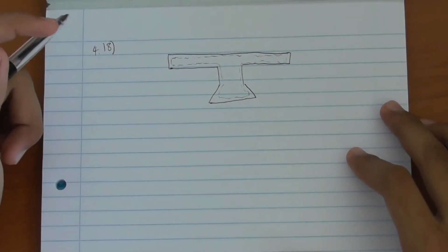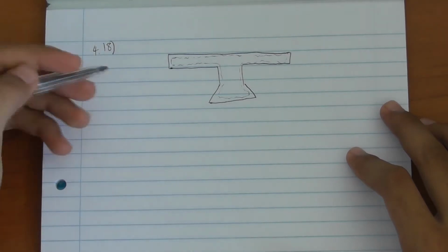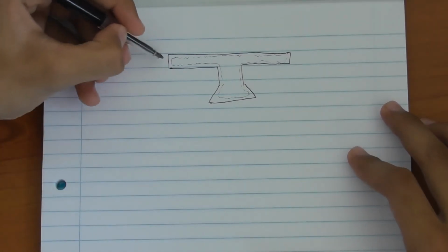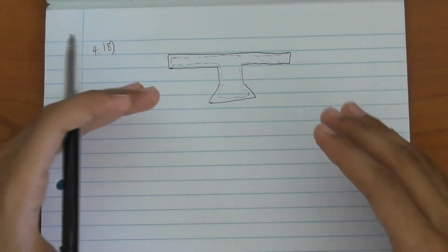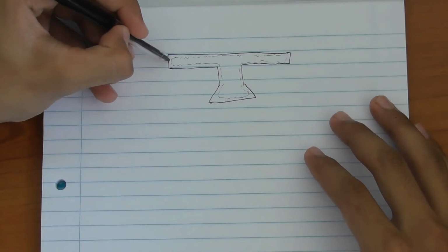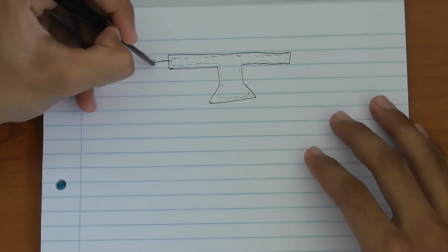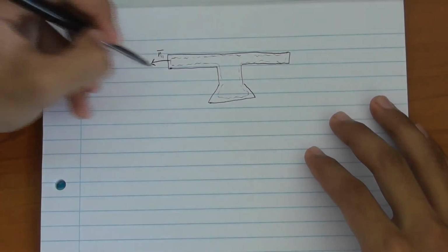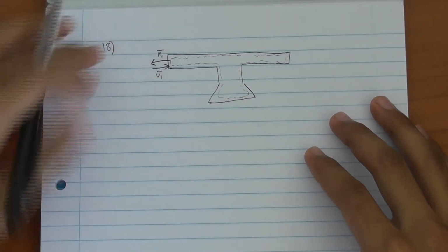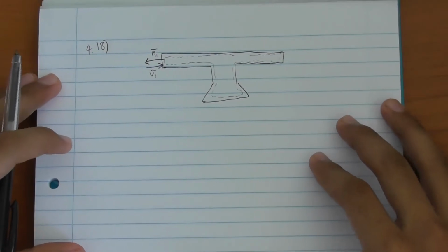All right. The next thing you want to do is fill in your normal and velocity vectors. So I know that my normal vectors are always perpendicular to the control volume and away from the control volume. So here we are perpendicular to and away from the control volume. I also know that my velocity is entering here, so V1 points inwards, right?